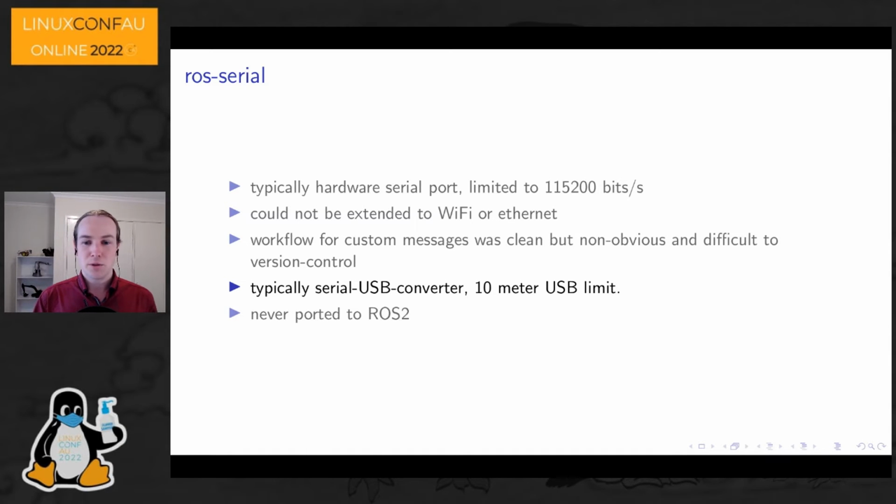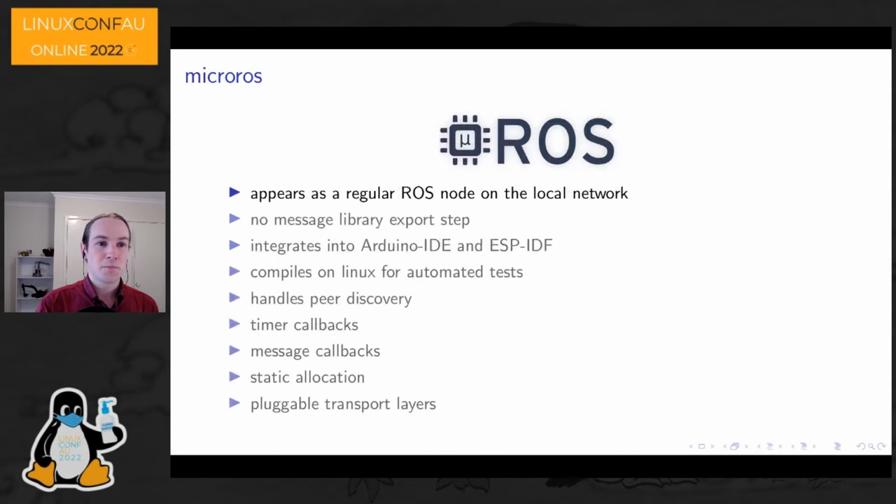Because the serial port on almost all Arduinos and clones used USB serial emulation, they inherited a 10-meter limit to their tether to a host PC. It was common to see wireless bridges, OpenWRT routers, or XBee radios, but they often doubled the cost of the actual robot. These limitations needed a systematic fix.